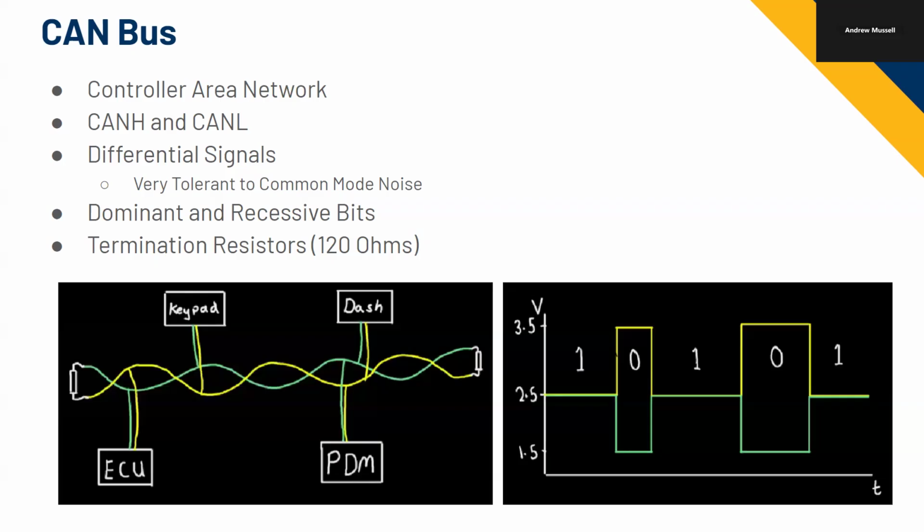Yeah. So after we go through the resistors, how do they actually get power? The lines? Yeah, so each PCB will have a CAN transceiver on it, and that CAN transceiver is communicating to the microcontroller over a UART bus.